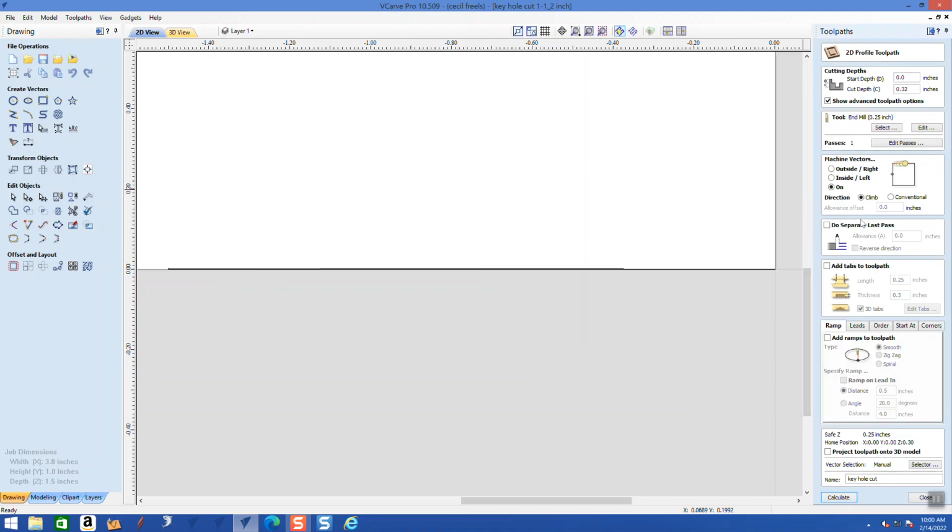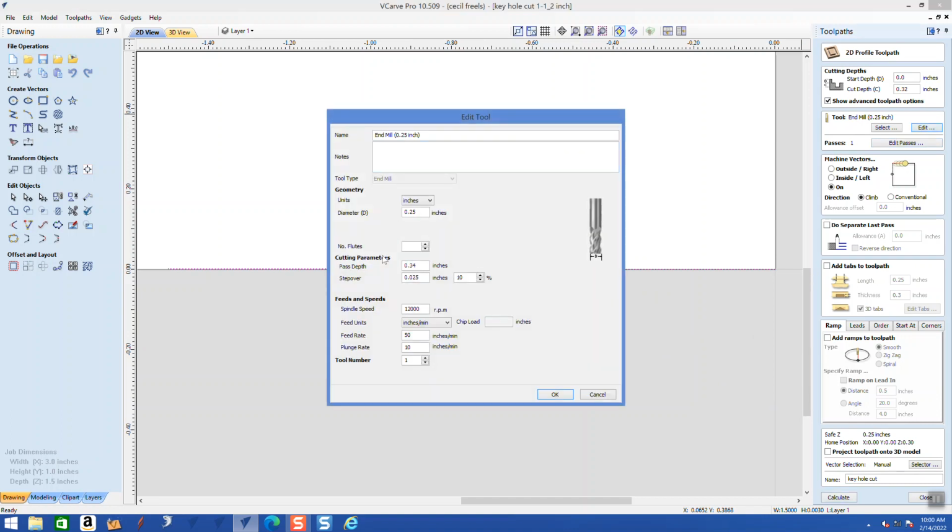So now we're going to double click on a tool, and it's a profile tool path. We're going to select this as our object that we're going to profile and cut. We're going to go to a depth of 0.32. We've come in here and edited our depth of cut parameter. See it right there? See how big it is? It needs to be larger than your cut depth, equal to or larger than. I chose a little bit larger than for safety's sake.